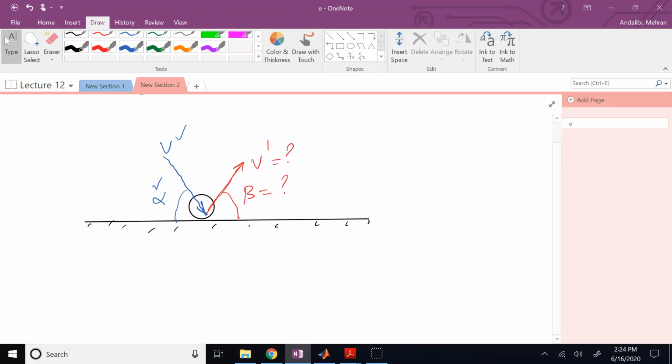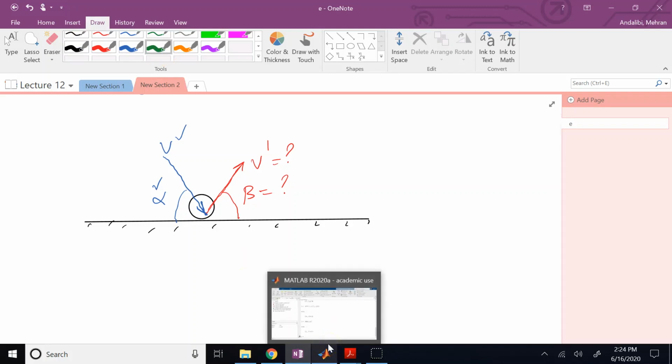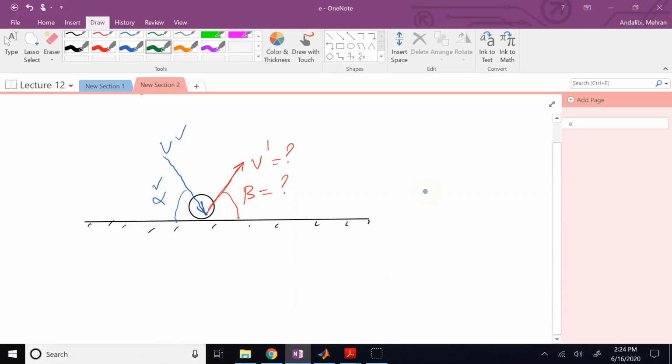So here, if you see the plane of contact, the tangent to both surfaces is the horizontal line. And the normal line along which the force is applied is what? It is the vertical line. So in this case, actually, you might say, well, I want to use x-axis to be vertical and y-axis to be horizontal according to those formulas. Yes, you definitely can do that, but in this case, since it's so simple, you might still keep your x and y axis as is. So don't change them. Use the same x and y that you use for projectile. But know that this x is now plane of contact or line of contact. Let's just write it like that. Plane of contact. And the y-axis is line of impact.